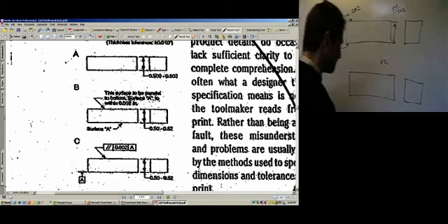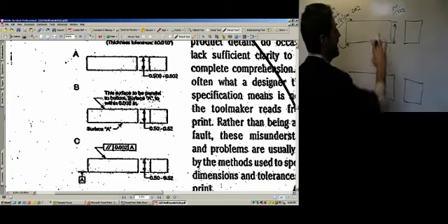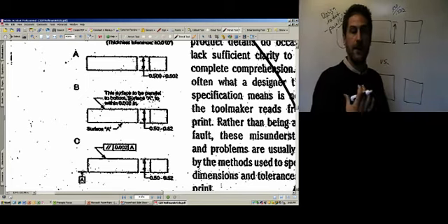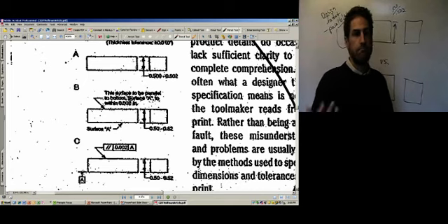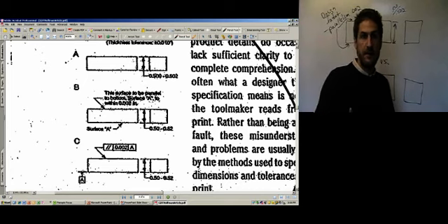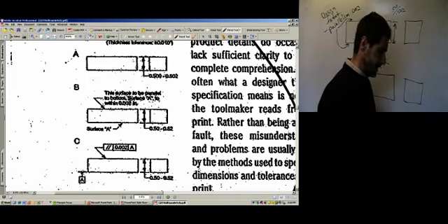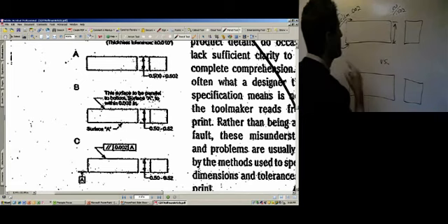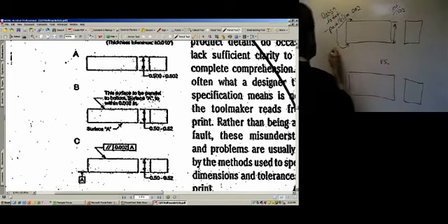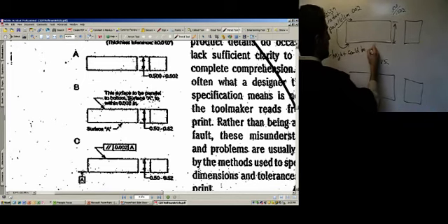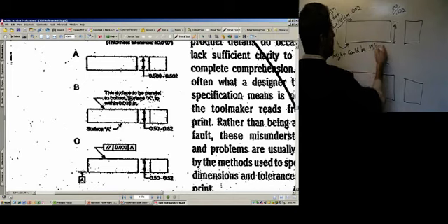other. Now, in terms of this height, the 1/2 inch height, the designer's not that concerned about it. It's desired to be 0.5, a 1/2 inch, but if it's even maybe 0.49 or 0.51, that'd be fine. So the second thing is that height really could be 0.49 to 0.51.